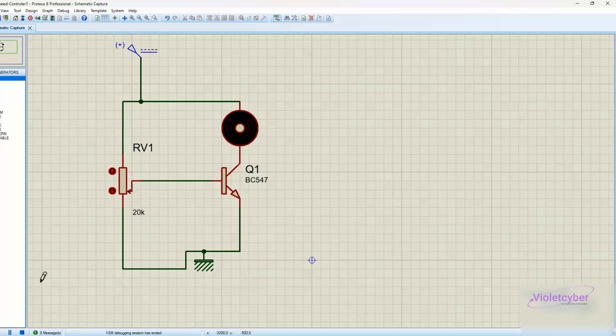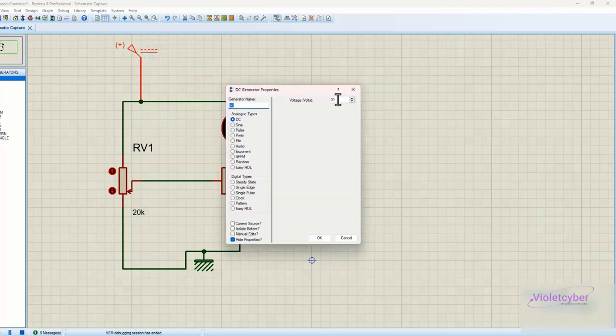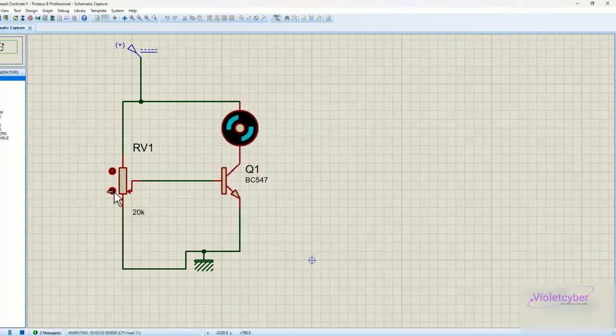I'm going to stop the circuit. Here I'm actually going to increase the motor voltage, for example, to 30 volts like this. I'm going to run the circuit again. And you see that because the voltage has increased, the motor starts to rotate. Now, as I turn the potentiometer again, you see that the motor rotates faster. For example, if I move it to here, it reaches its maximum speed, which you see here. You can easily make a circuit that controls the speed of the motor.